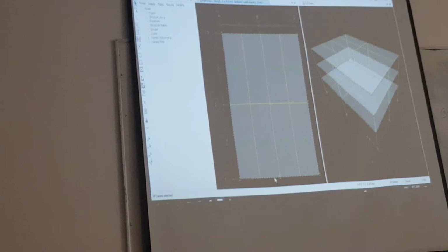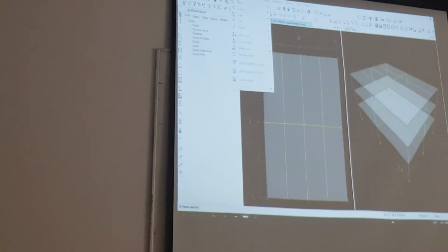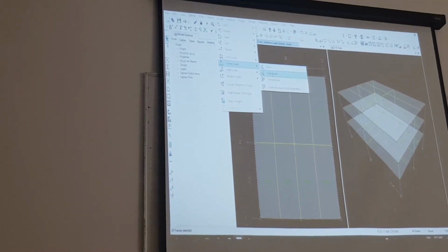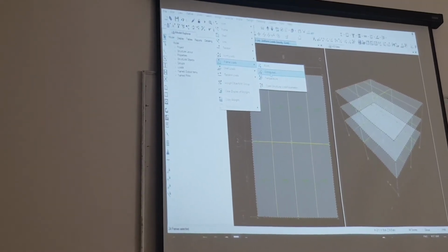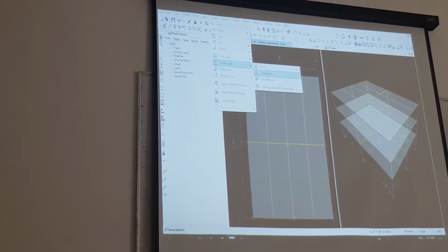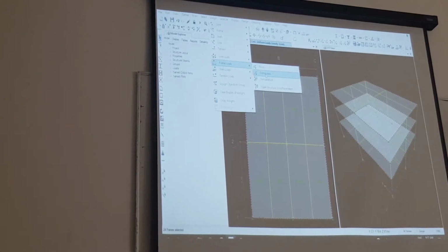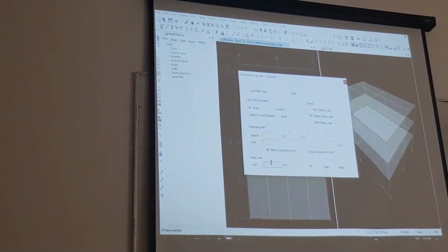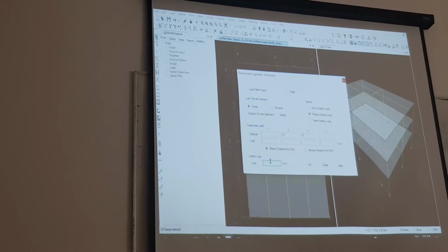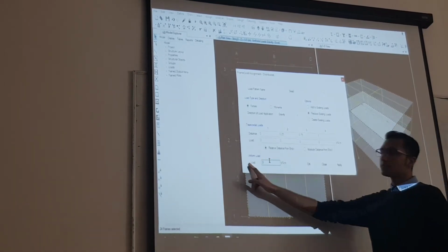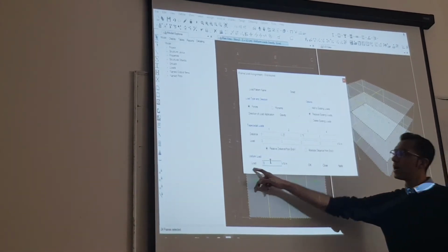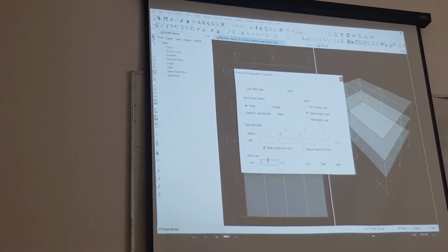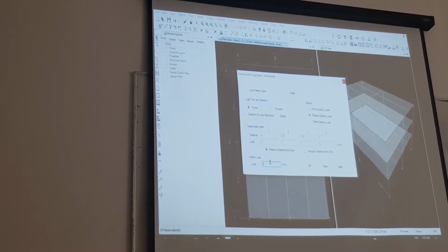Now, in order to apply the wall loads, go to assign again. This time you are going to apply the frame loads. And in frame loads, you are going to click on distributed. Since you have a uniform load, type at the bottom, let us make it 2.5 kilonewtons per meter. But you have to calculate it for your project, right?